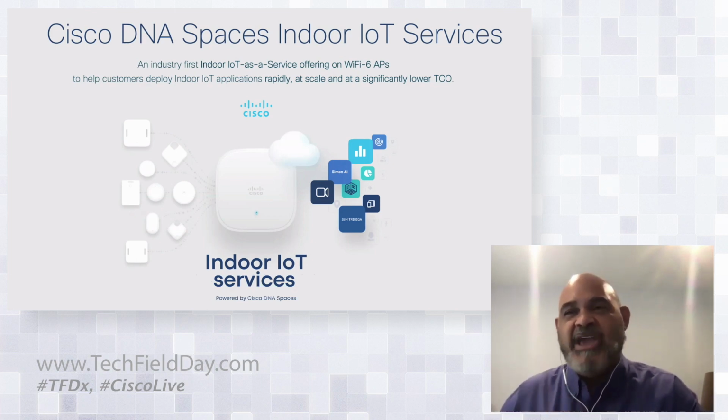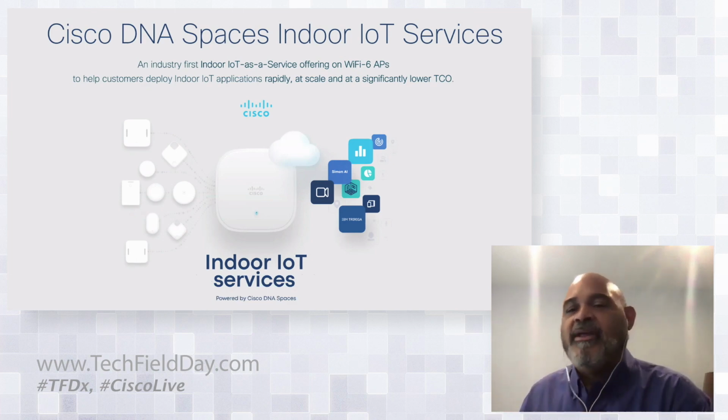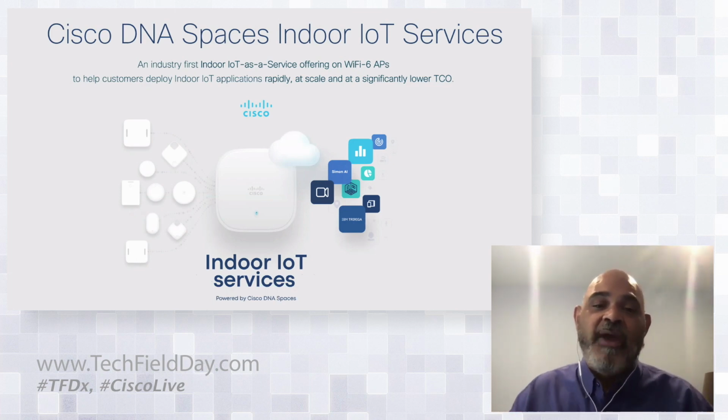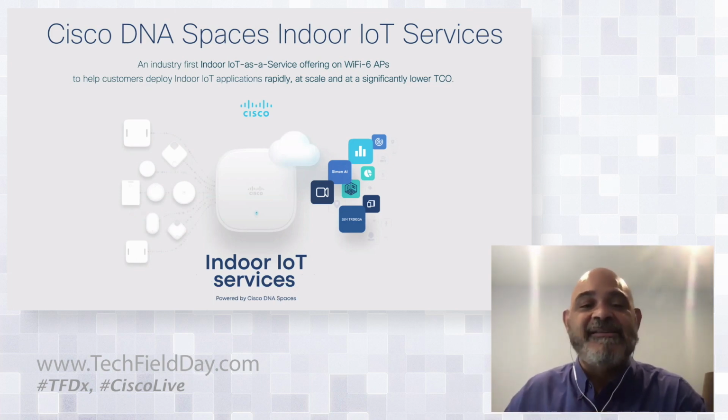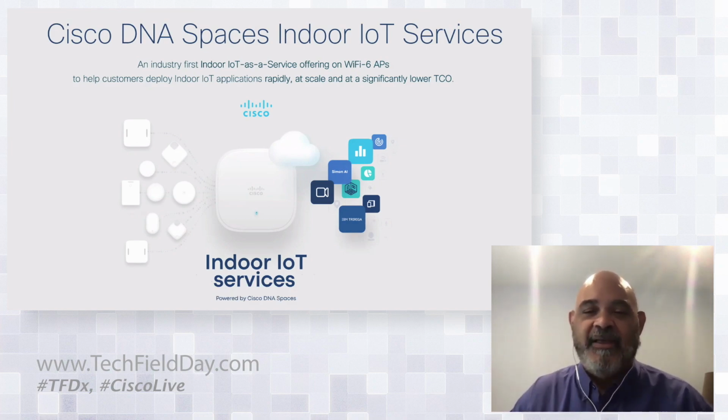So that's this step change from APs, which for years and decades had been all about the 2.4 and the 5 gigahertz with Wi-Fi modulation. Now we're also going to be able to do a two-way handshake with BLE devices to do things like, hey, I need to upgrade the firmware on this particular BLE tag, or I need to tell this particular BLE tag, hey, instead of sending a beacon out once every 100 milliseconds, I want you to slow down your rate of battery usage and send this beacon out once every 600 milliseconds. That type of two-way communication is inherent in what's possible in our 9000 series Catalyst APs.